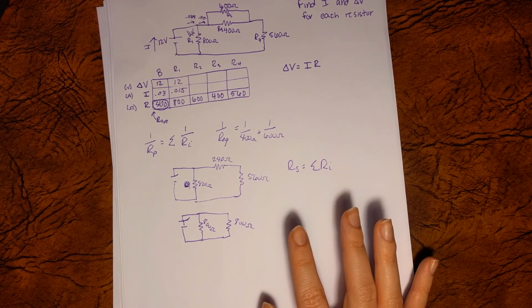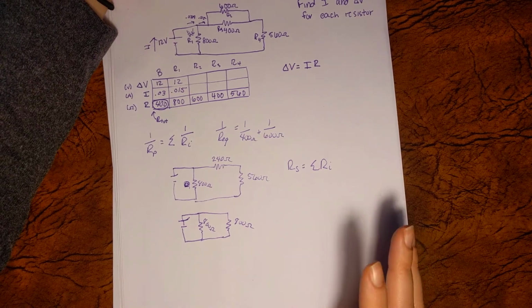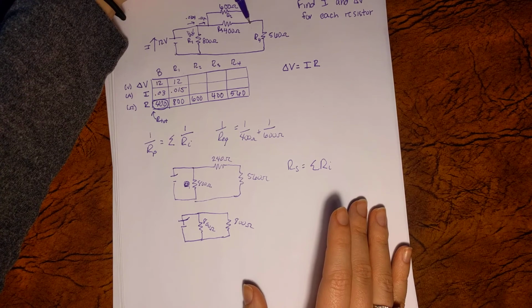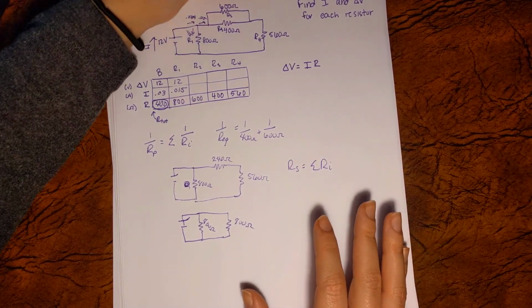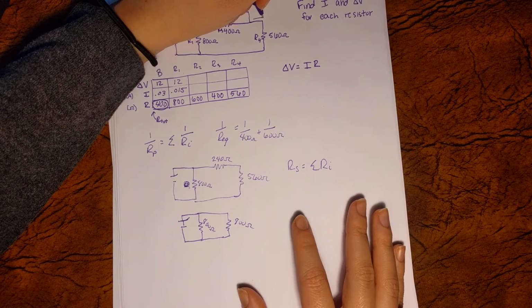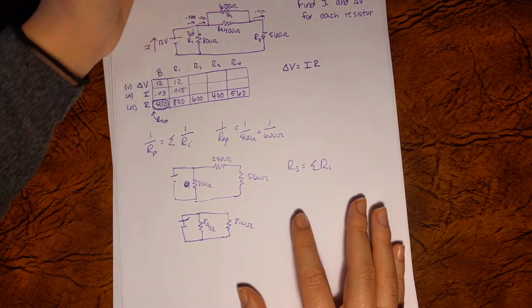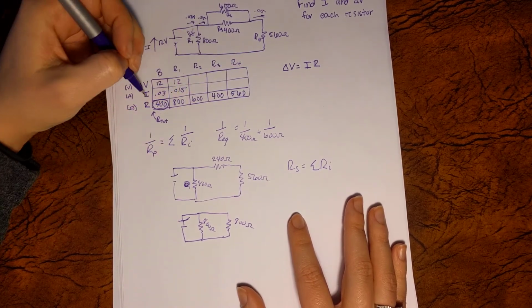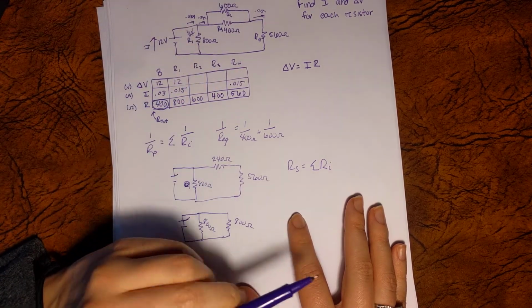What could be useful here? Looking again, we're dealing with the junction law. Once the current splits, it has to come back together, and once it comes back together, the total number of charges didn't change per unit time. So coming out of this junction has to be 0.015 amps again. That means running through resistor 4, our current is 0.015 amps.